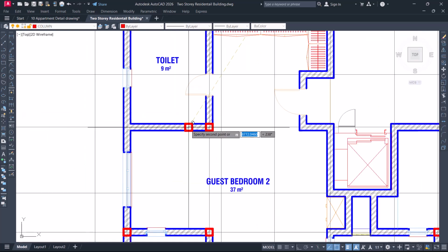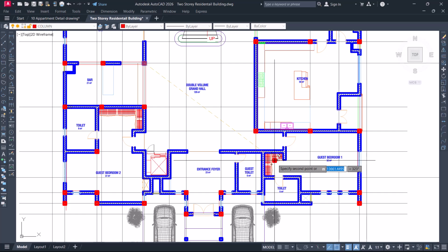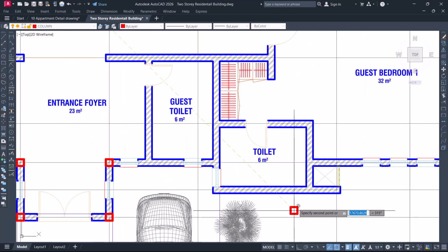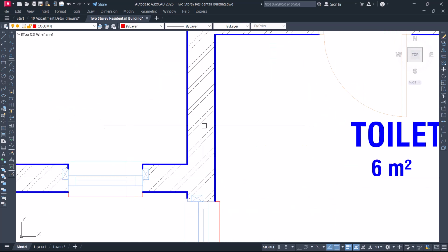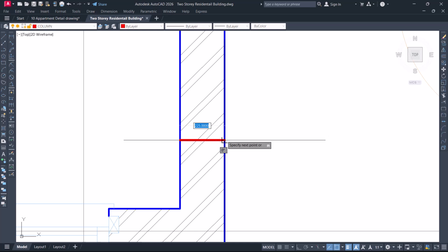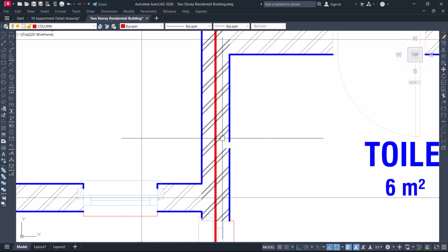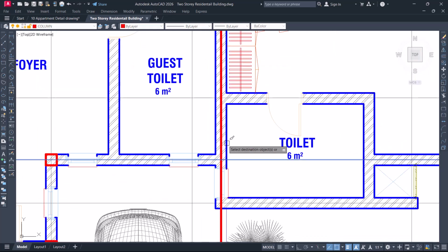Okay, that's fine. So again now, I need to create, let me see this place. A line needs to be here, a grid line here, or at this point. So I'll divide this line again by 2, like this. Okay, and then XL, enter, V, enter, and then click on this here and remove this one. So again, MA, match property, match this to this.